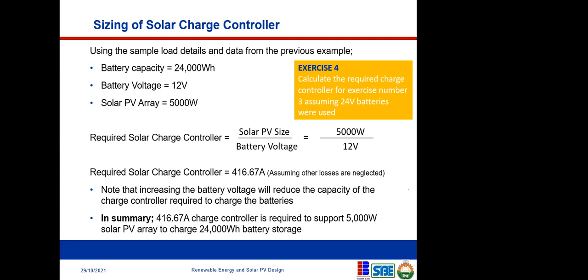Except you're making a certain assumption, like you rightly said, that for 6 peak sun hours the sun is shining, and on the assumption again that all the energy coming from the solar system goes to charging the battery. Based on those assumptions, we can calculate the amount of time it's going to take for this battery to be fully charged. Already for this analysis, we have assumed additional days of autonomy.